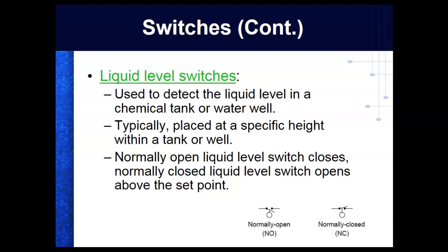Yes, it's a flow switch. Yeah, in fact, it's the same switch. If you ever pulled up the sensor on that, you'd see a little float. It uses a potentiometer that comes up and moves with the float, and that's where it gives you your analog signal. Then when it gets down to a certain level, it trips your need fuel light, or whatever you're saying.